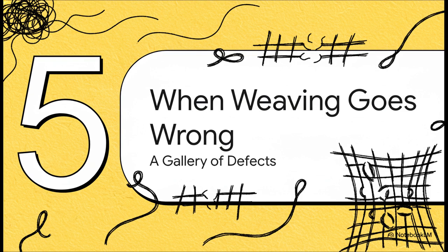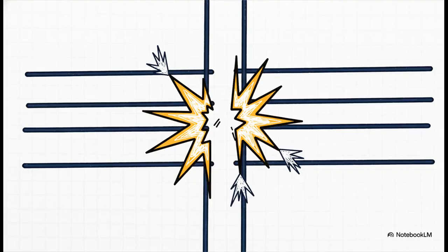So, what do these tension-related failures actually look like in the real world? Let's take a quick look at the Rogues Gallery of common weaving defects. This one's a classic, a broken warp. This happens when a single warp yarn, under way too much tension, just gives up and snaps. The loom keeps on going, of course, but now there's a missing thread, creating this visible, structural flaw that runs all the way down the length of the fabric.